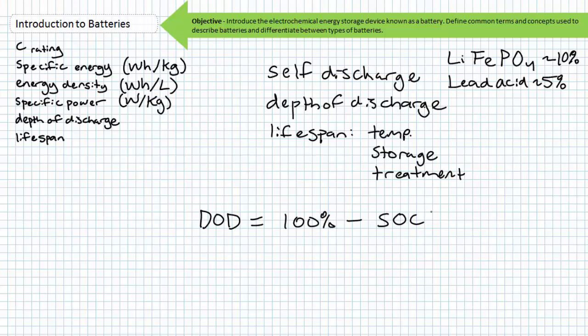Depth of discharge is essentially the opposite of state of charge. If state of charge represents how much gas is left in the tank, depth of discharge represents how much gas you've removed from the tank. As mentioned previously, a full discharge causes strain, and each cycle permanently robs the battery of a small amount of capacity. Additionally, batteries that regularly experience a high depth of discharge and go long periods of time before being recharged will have a shorter lifespan than those that regularly experience a shallow depth of discharge and are immediately and properly recharged.